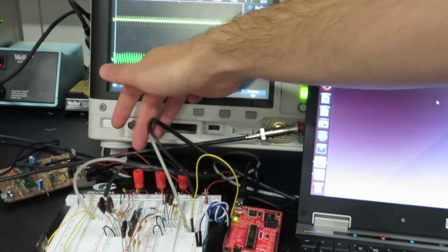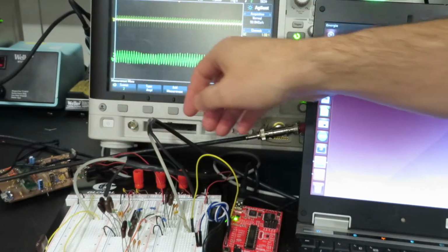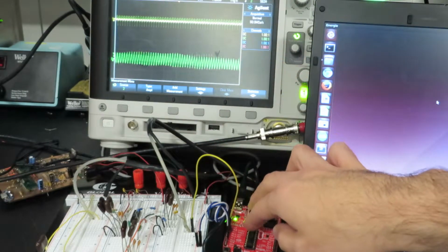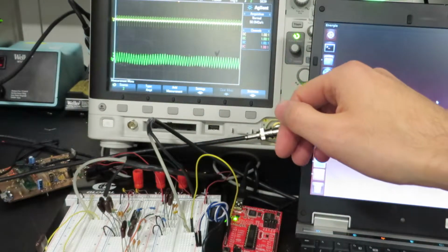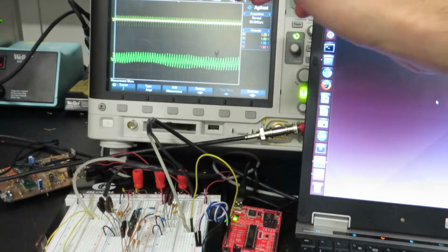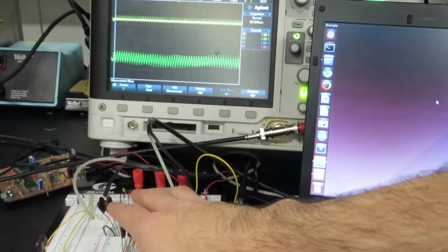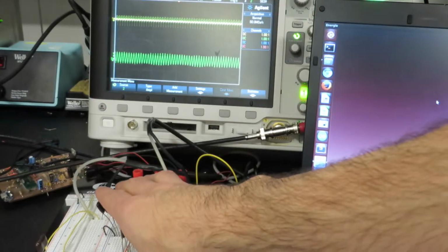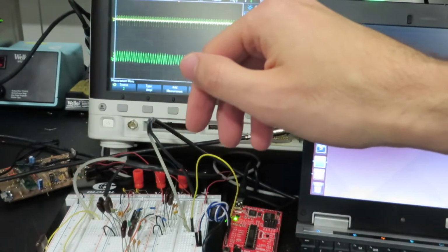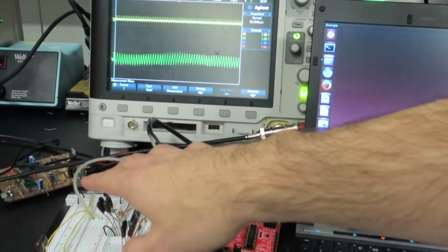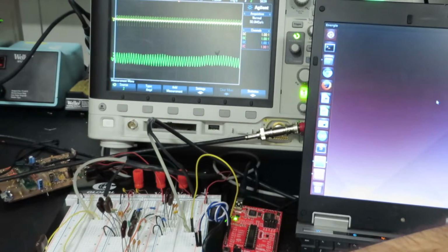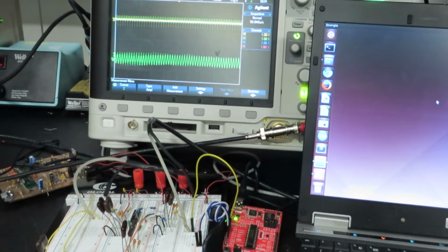It's got plus 5 volts, minus 5 volts, 3.3 for the microcontroller, as well as ground. The audio filter is running on the breadboard because I botched the audio filter on the PCB. So we're connecting through the breadboard. We've got a microphone that's going to do the input, and then we've also got a function generator.